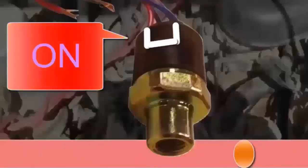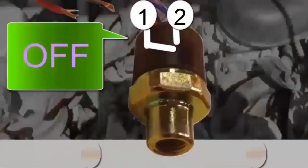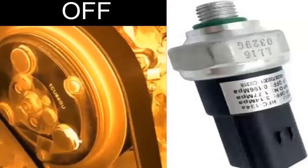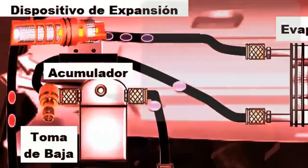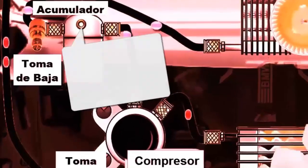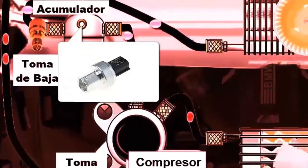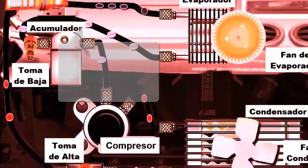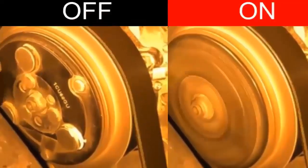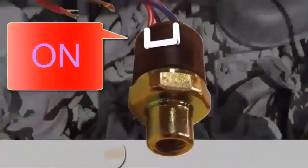The low-pressure switch in automotive air conditioning systems is a 2-pin or 2-wire component located in the system's low-pressure line. In many cases, it is found on the filter or liquid accumulator, just before the compressor suction line. This switch acts as a safety and control mechanism designed to deactivate the compressor when the suction pressure drops to levels that could be harmful to the system's operation.